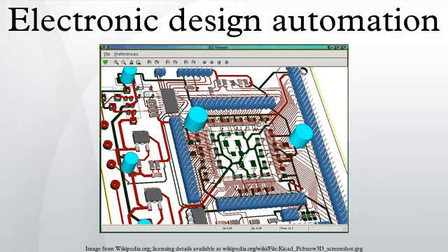Current status: current digital flows are extremely modular. The front-ends produce standardized design descriptions that compile into invocations of cells, without regard to the cell technology. Cells implement logic or other electronic functions using a particular integrated circuit technology. Fabricators generally provide libraries of components for their production processes, with simulation models that fit standard simulation tools.